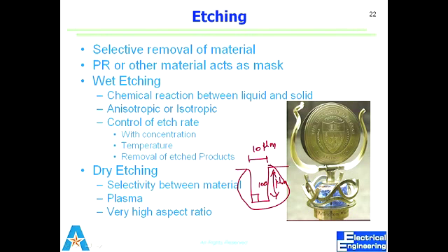Same is the case in dry etching. Once you have the product, you want to suck it out, vacuum pump it out, so more reactant can react and do whatever it's doing. So in dry etching, we have selectivity, again the same concept, but we create plasma in etch. In liquids, we just have those chemicals coming in contact. In dry etching, we create plasma.